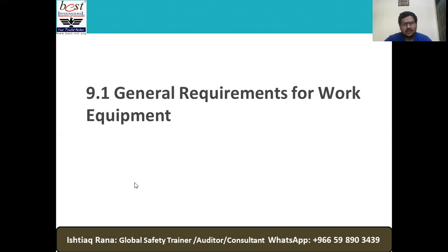General requirements. If I'm going to buy a work equipment, what are the requirements? Based on which international standards does that tool have to be manufactured, and quality must be validated before I even decide to purchase it. For a lot of electric tools, you're going to see UL listed must be there, like Underwriter Laboratories, or FM, Factory Mutual, or maybe the CE mark, a kind of protection mark. That is a validation of quality. Otherwise, equipment without UL or FM or some other mark wouldn't be acceptable, especially in Saudi Arabia, and the same case for Sadara for sure, inshallah.